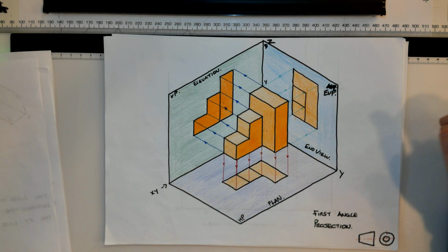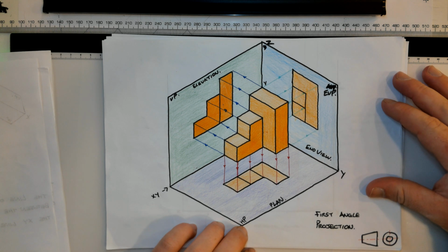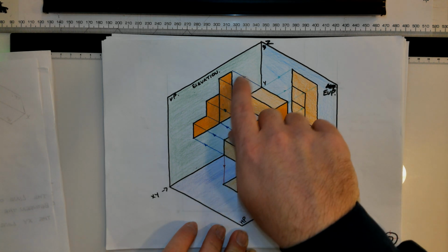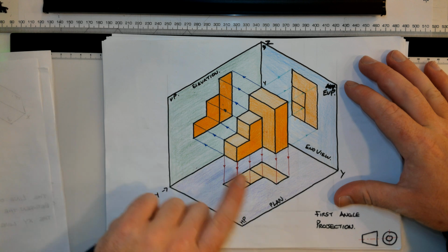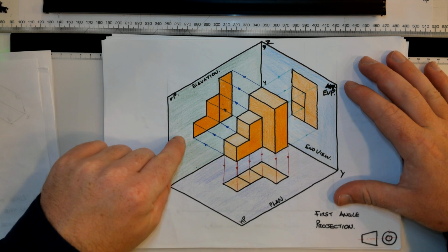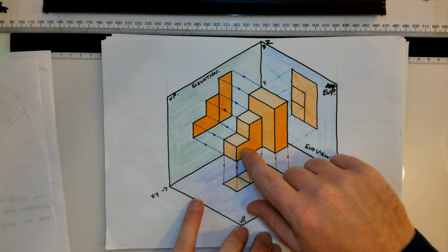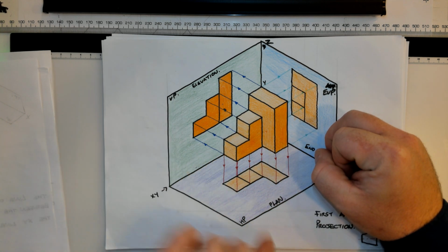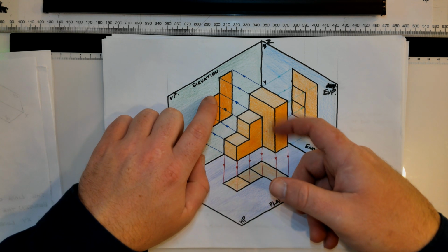So here we have a simple geometric object comprised of cuboids and cubes, mainly square faces and rectangular faces, which makes it quite easy. If we look, this face here will be the front because it's been projected onto this green vertical plane, which produces our elevation. Now, these projection lines are perpendicular to this face, so all we're going to see is an edge view of all these side faces. So for example, if we look at the different shading here, we're going to see the dark orange faces when we look in here. And we're also going to see the edges of all the side faces.